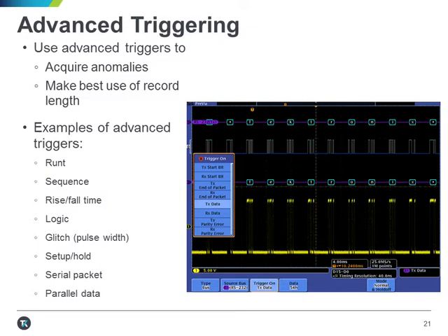For years now, some oscilloscopes have been able to trigger on a combination of inputs. What we call logic triggering allows you, for example, to tell the oscilloscope to trigger when all channels simultaneously show a logic high. More recently, oscilloscopes are able to trigger on serial data as it occurs on the input channels. So, for example, you can tell the oscilloscope to trigger when it sees an ASCII question mark on an RS-232 serial bus. I'll talk more about serial bus options shortly.